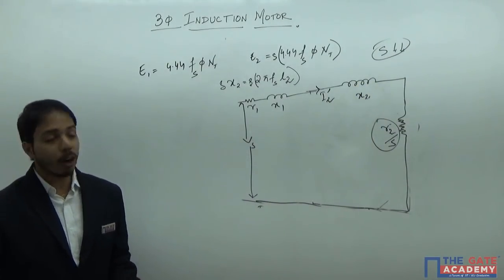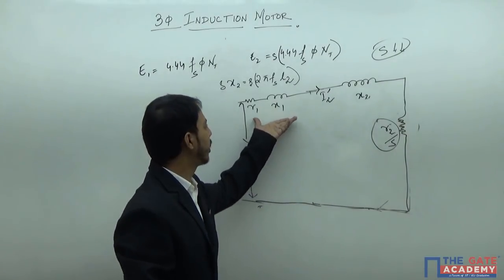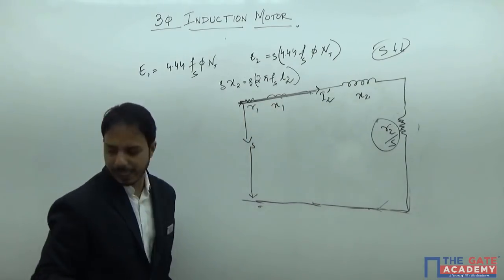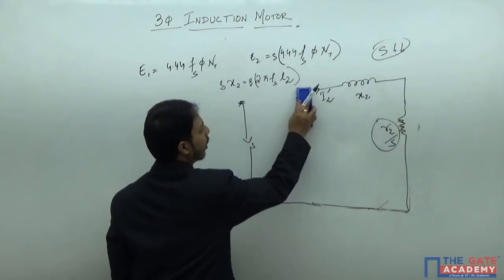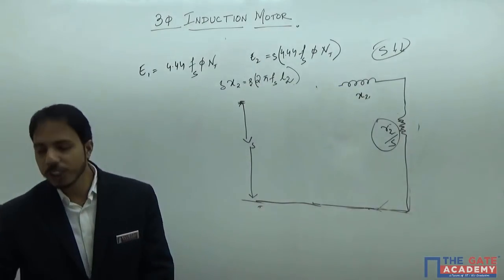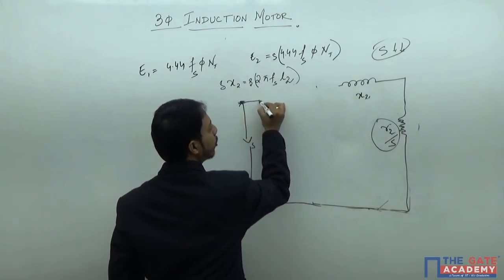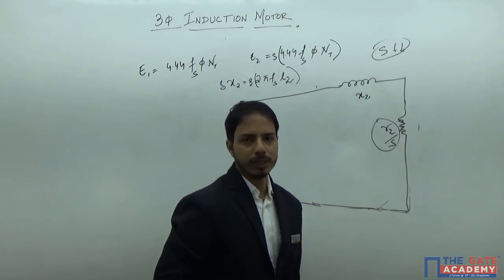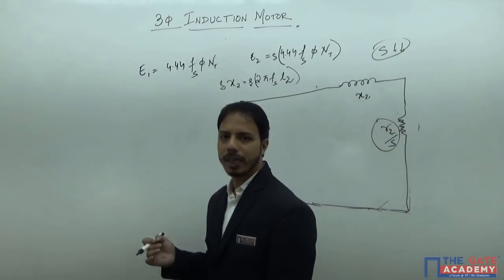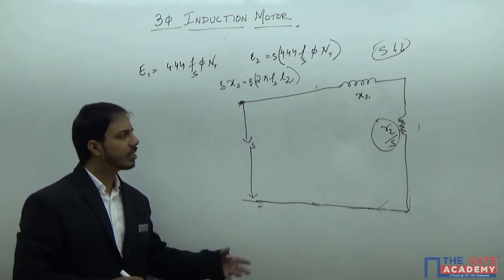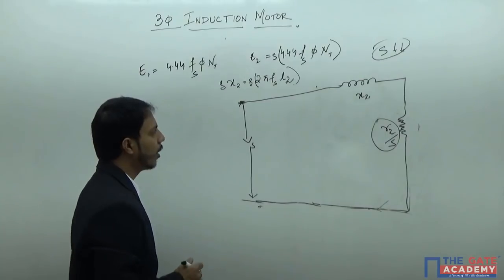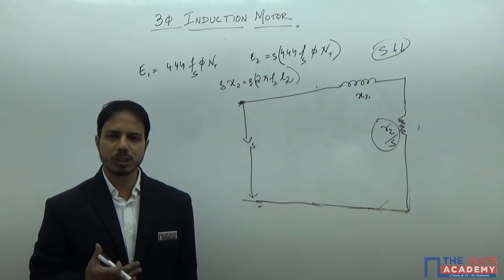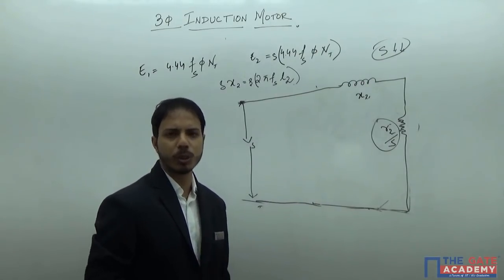And not even this, sometimes in questions they will say to neglect the stator impedance, right? In that case, you have to neglect this particular thing also. And if you see the questions in GATE, almost in every question they will ask you to neglect the stator impedance, or they will tell you to take the best approximation case. So I will stick to this for timing. My sole reason for this lecture is to make you realize how approximations are going to make our topic on induction motor easier.